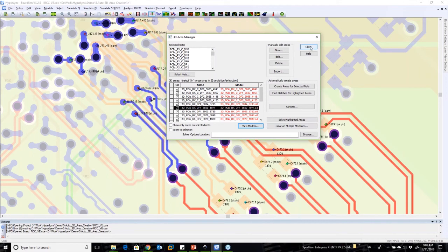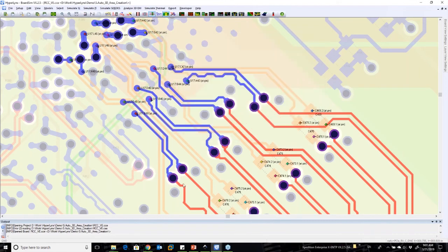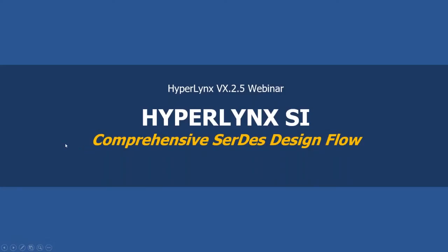Now that becomes part of the simulation. So we'll use the standard transmission lines until we get up to that area. Then they'll switch over to the S parameter model for the VIA structure, and getting that final bit of accuracy so that we more completely match up with what's actually going on. So that is the demonstration part that I wanted to cover. Just finish up with a few extra slides here.